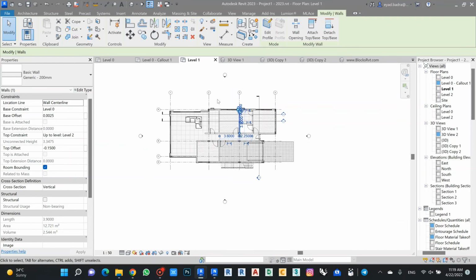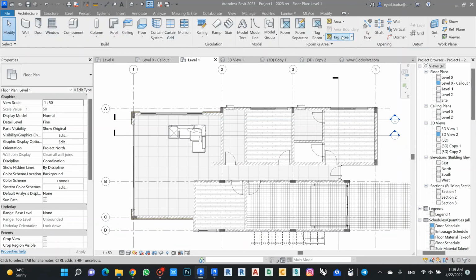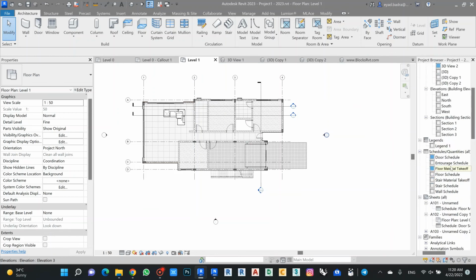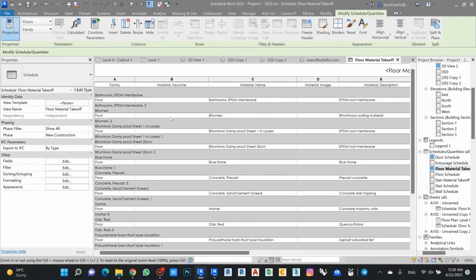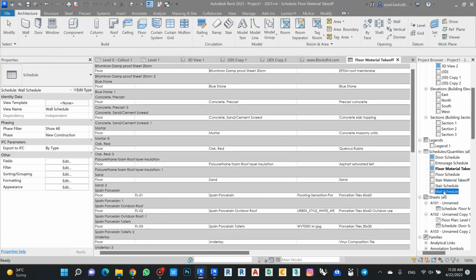So it's very important to import item by item in Revit before we work in this family or in any architectural element. It's important to add first the simple code and the simple name, because it will be easier later in my quantification. Because if I go back to, let's say, material takeoff, my quantification here, I made one before quickly, and let's say this is the finishing wall schedule.